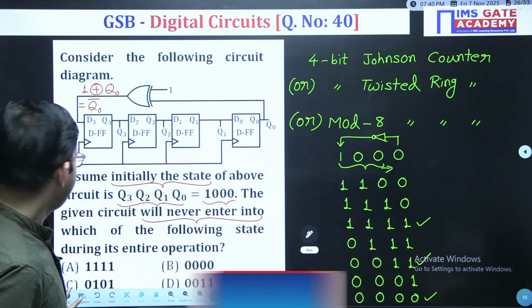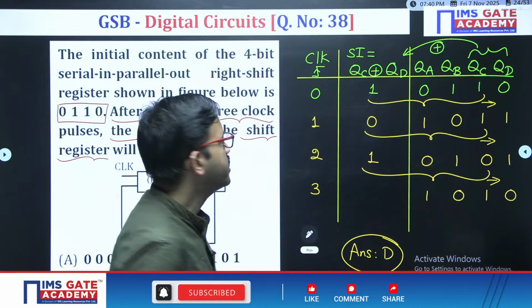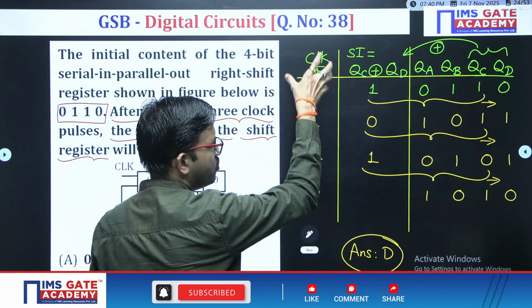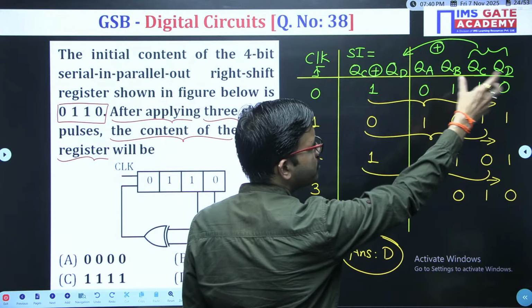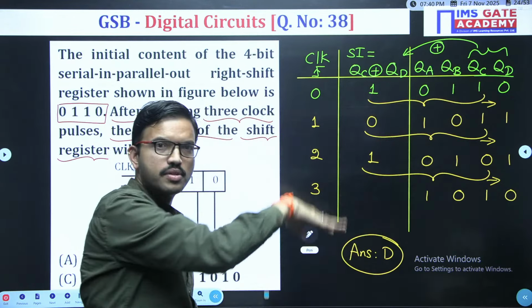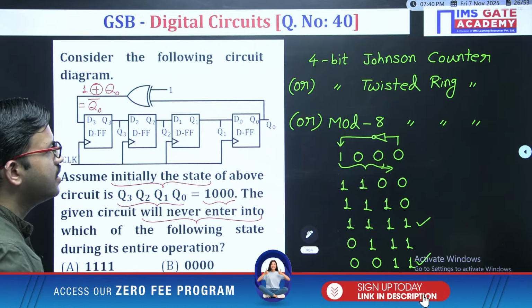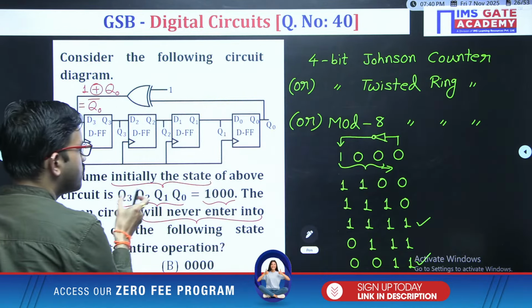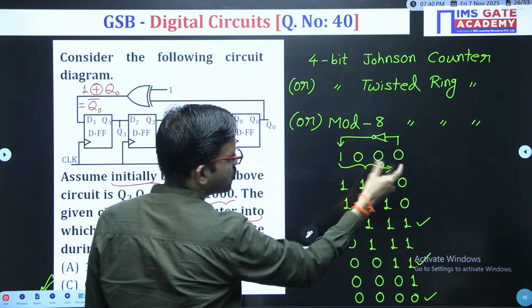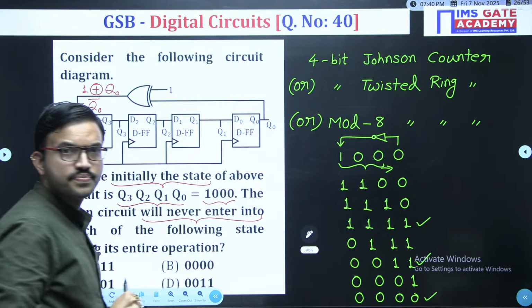Yeah, Suganya, it is very simple. As I mentioned, this is the actual method. See, clock signal, you will be writing first column, then serial input is Q0 bar, then Q3, Q2, Q1, Q0. You have to follow this tabular form method. But instead of discussing this one, I have mentioned the same thing here in short. Whatever the 4 outputs you are having, Q3, Q2, Q1, Q0, that I have represented, and here only shifting operation is taking place. Yes or no?